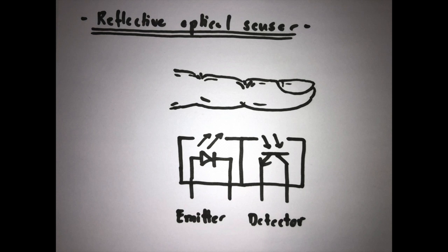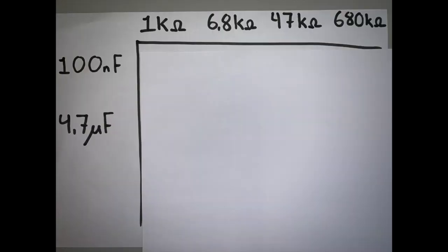In this exercise, we built a circuit that filters this infrared light and uses the AC component peaks to light up an LED or a diode. So when the LED light flickers, it indicates a pulse, or the AC peaks.